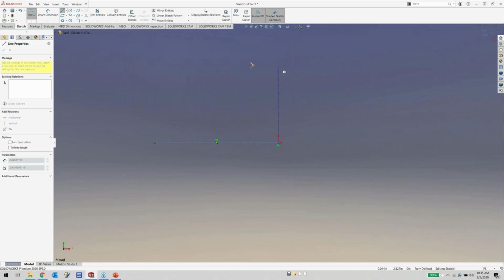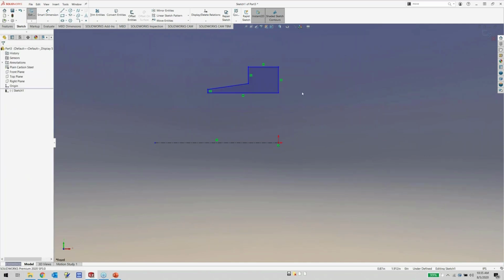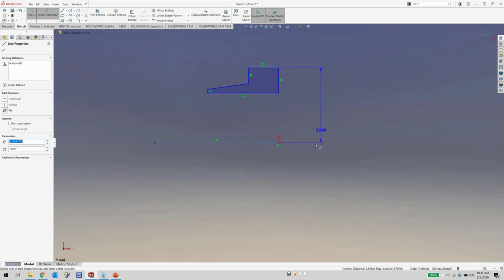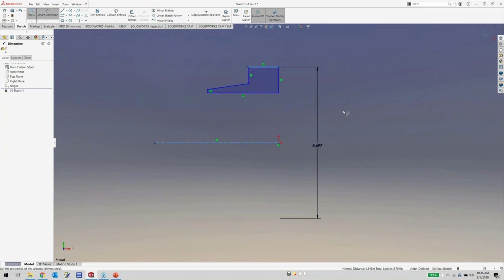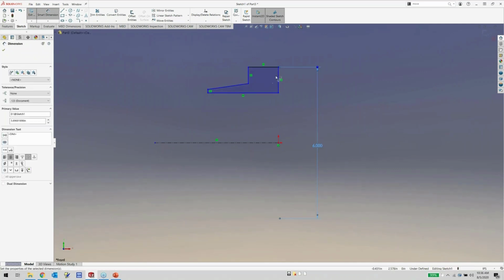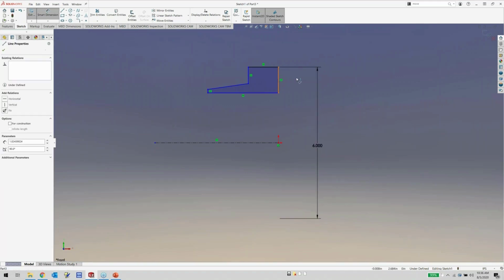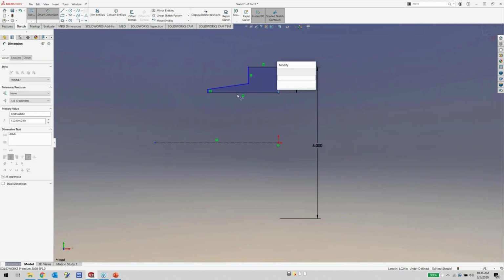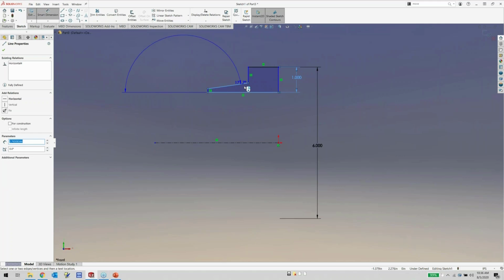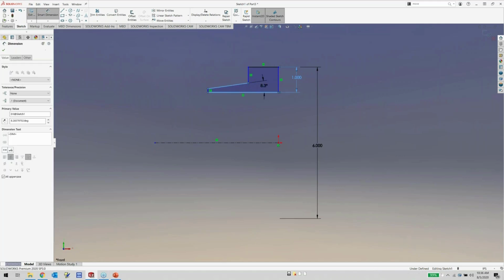When we do this, we want to make sure that everything in the drawing has dimensional values. We want to make sure that everything in the model can be shown on the drawing, and that way everything is there. So I'm going to use a 6-inch flange, for instance. Give just a few dimensions on here so that we have enough to go by. Let's make it 1 inch, and then we'll give maybe an angle and a distance here so we can show a little bit more. All right, that looks good.